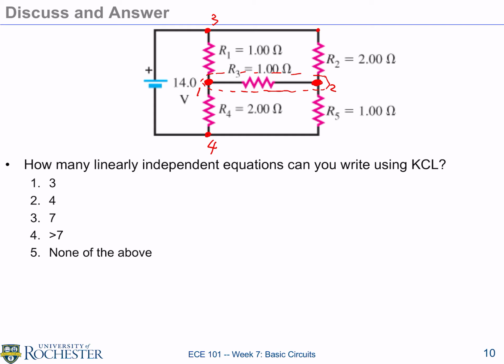Anytime you have a wire, they're all idealized in the circuit, you can cut any segment of wire and just stitch them together if you wish. So I can imagine this little wire is all gone, so I'm just going to move these two together. You know what I mean? So it's the same node. So we have 4 nodes, but the answer is we have 3 equations.